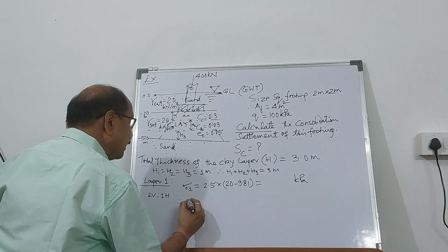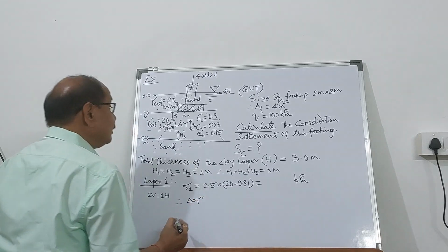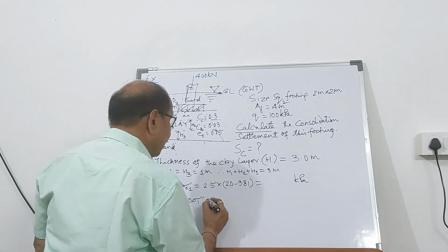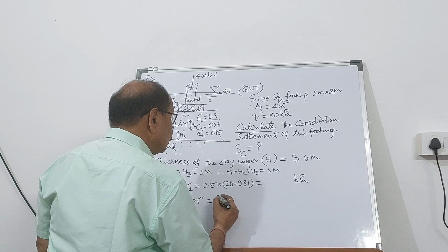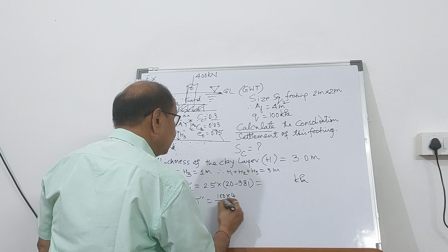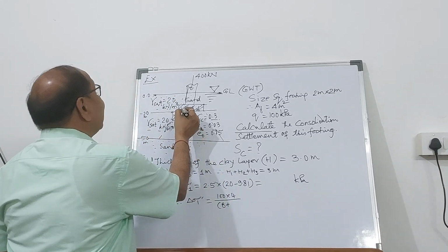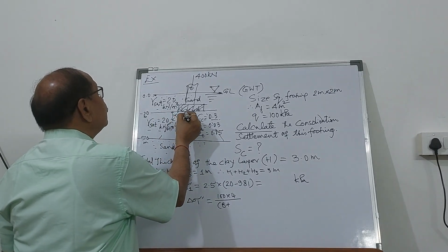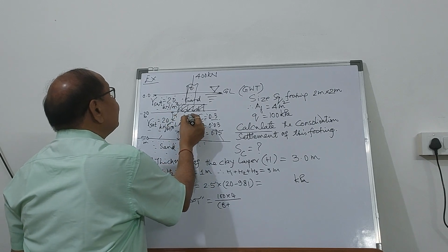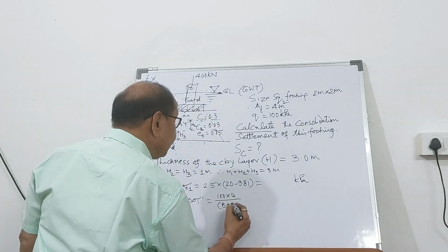Therefore, the average increase in effective pressure due to the application of the load is called delta sigma 1 prime, equal to the intensity of loading multiplied by area of the footing divided by B plus, at the midpoint it is H1 by 2, so 0.5 by 2 on the left hand side, 2 vertical, 1 horizontal, and on the right side. So it becomes B plus